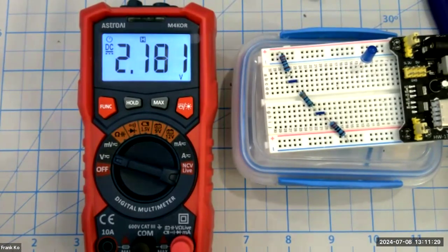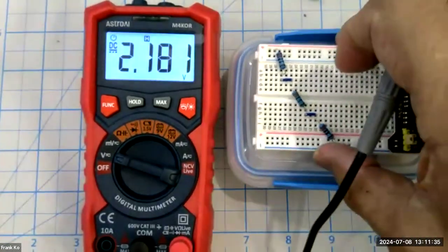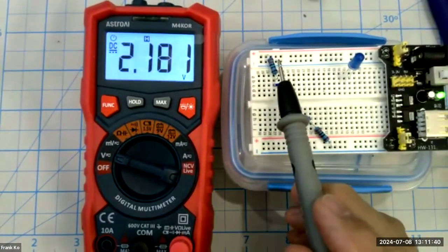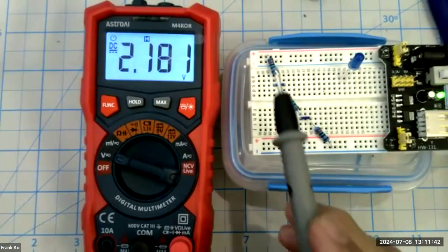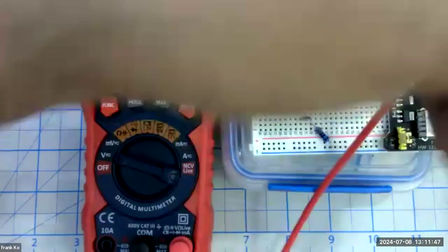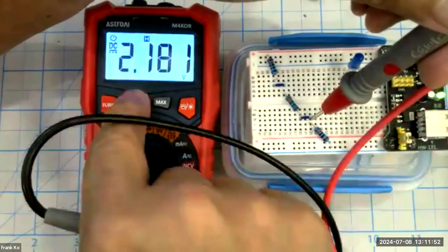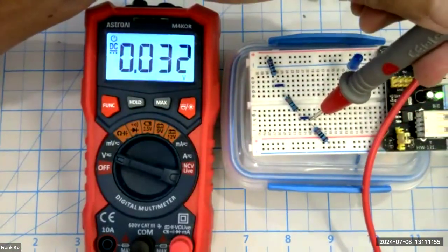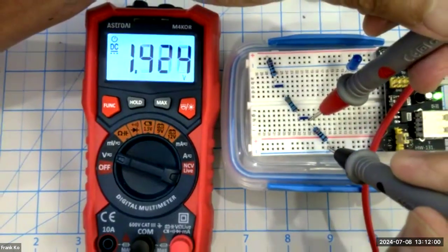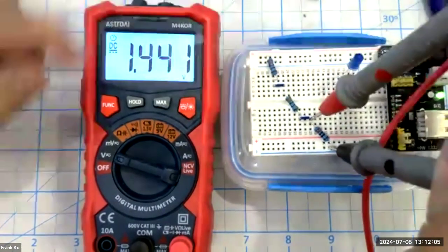Let me come back here. And now let's go ahead and make a measurement across the third resistor and see what's going on there. Why I'm not measuring anything, because if I'm measuring voltage across the first resistor, second resistor, I must have current flowing through here. And so let's see what's going on with the third resistor. Maybe I'm not connecting this properly. Let's go here. Oops, take off the hold. All right, I'm expecting something close to 1.43. Let's go ahead and measure. Oh, okay. That's the answer. I get, oops. Hold steady.